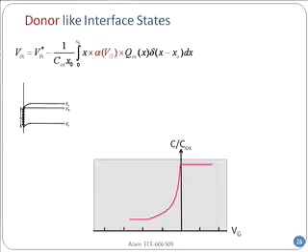So let's see what happens. Now follow with me carefully, because this is something the professors like very much, and let's see whether I can explain to you. What type of substrate do I have? This is an N-type substrate. So therefore you can see my CV characteristic is facing the other side than what I typically draw. Now let me assume that these are all donor-like traps.